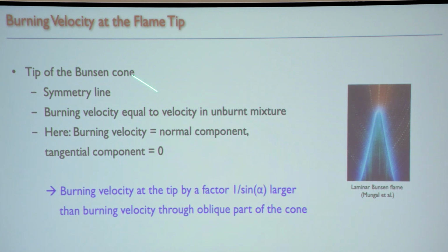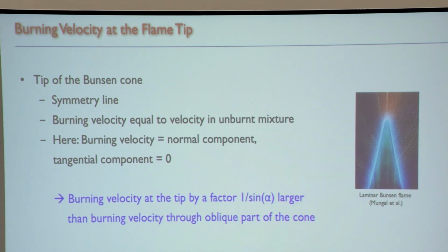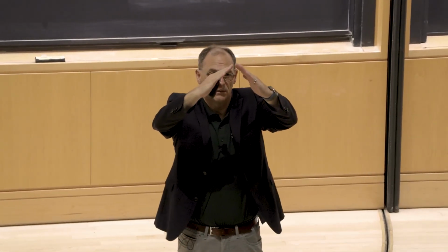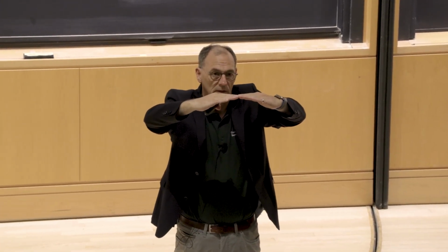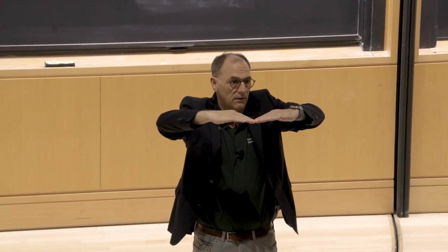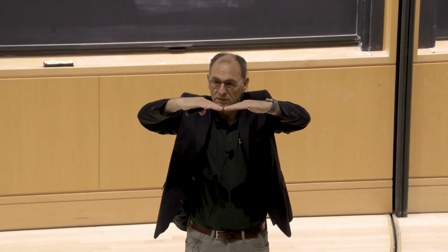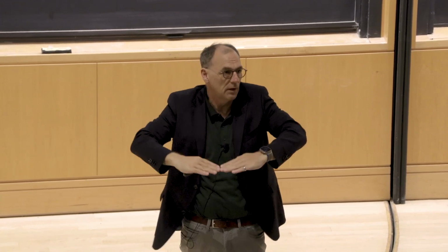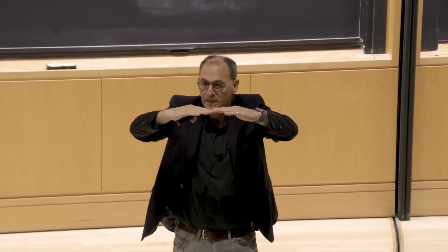And then here's one other thing that's interesting about this flame. We said that you get this cone, and now if I decrease the velocity, the angle gets larger and larger until the flow velocity is exactly the burning velocity, and then it should be flat, and if I decrease a little more, it starts burning into the burner, right?